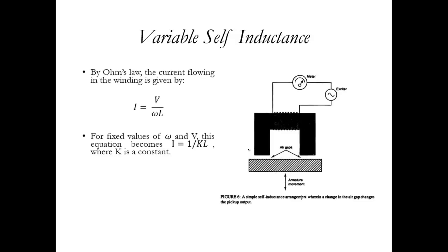Now, in this one, we have a similar arrangement where, rather than E, we can have a simple U shape or something like that, where we have a coil. Again, it's excited by an alternating current and creates a magnetic field. Then we have an armature, or a ferromagnetic material, that goes up and down based on the object that it's connected to. Then there's a reduction in the air gaps, and accordingly it changes the inductance, that is, L is changed, increased or decreased.